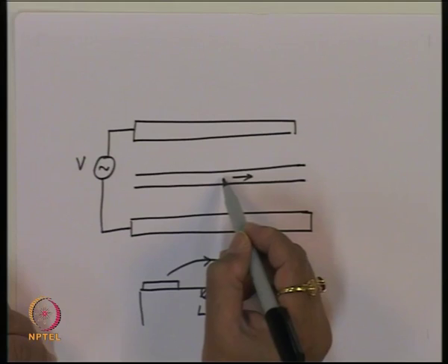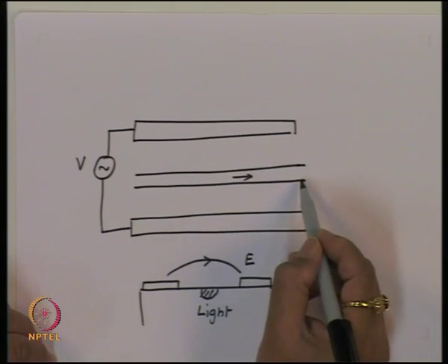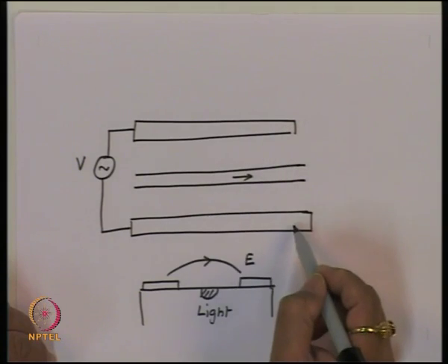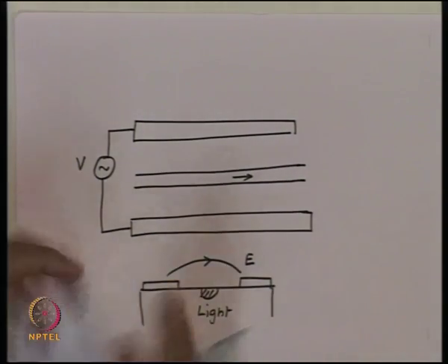If there is a velocity mismatch, for a certain portion of light, you will see that for some time the signal voltage is positive, both are traveling together, but since they are not traveling with the same speed, sometimes you will see positive voltage and negative voltage interacting with that light. After some time, when the light has moved to this location, there is a difference in phase, so here this becomes positive, this becomes negative, so phase is reversed.